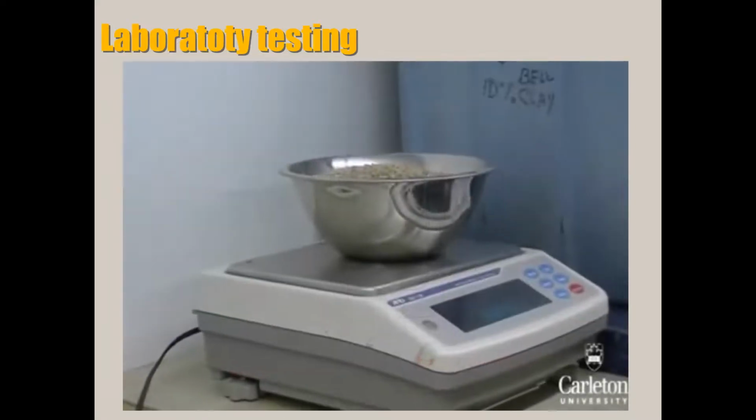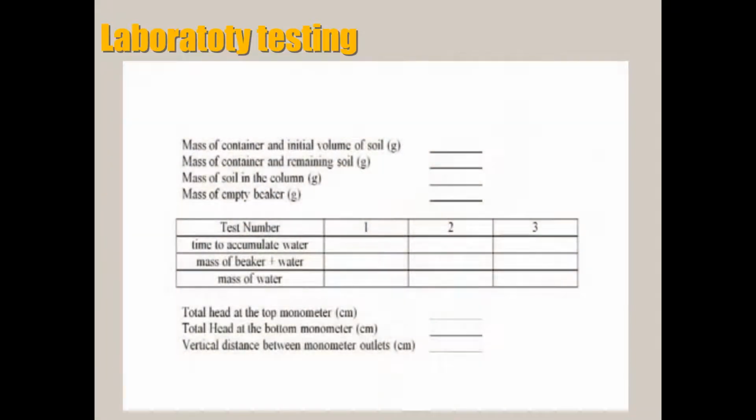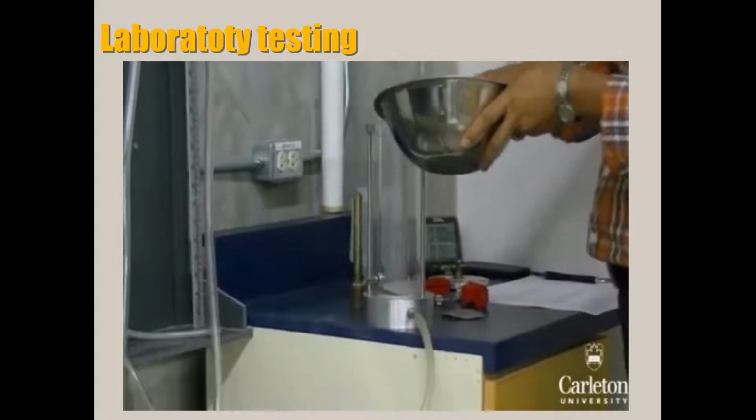First, obtain about 1 kilogram of coarse soil and place it in a container. This should be enough to fill the test cylinder. Record the mass of the container plus the soil in a table. Place a screen at the bottom of the cylinder. This prevents the soil from being carried out.